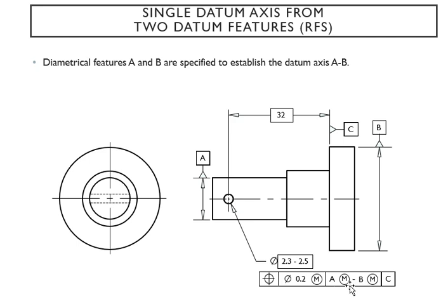So A and B have a maximum material condition. C doesn't have it, so we can combine A and B together because you're sharing the same axis. All three datums are sharing the same axis, but you cannot put C with A or B because of the material condition. A and B have the same material condition, so you can box them together.